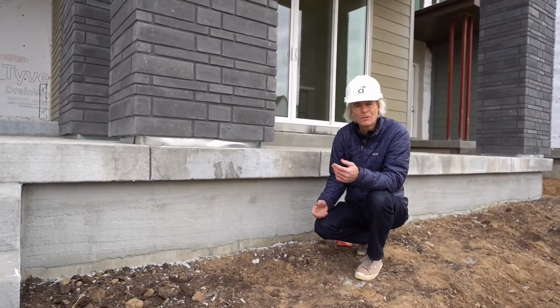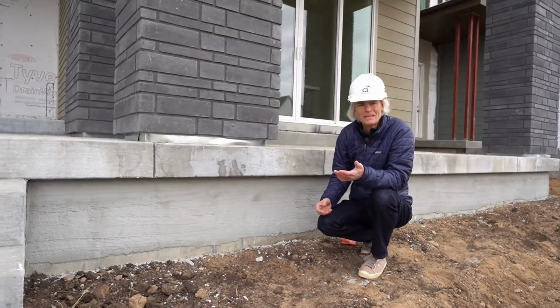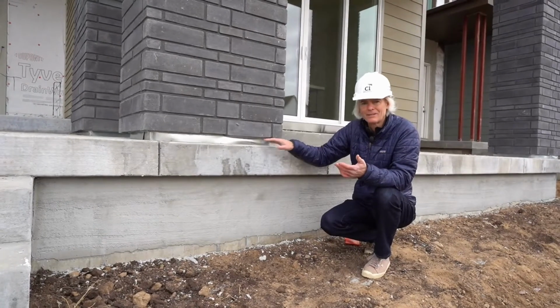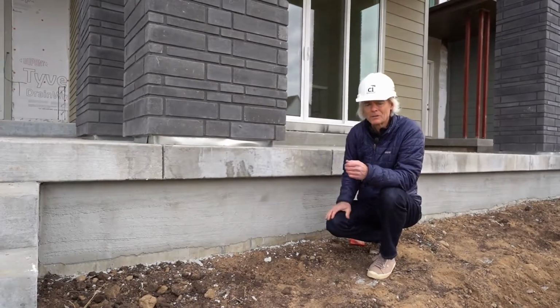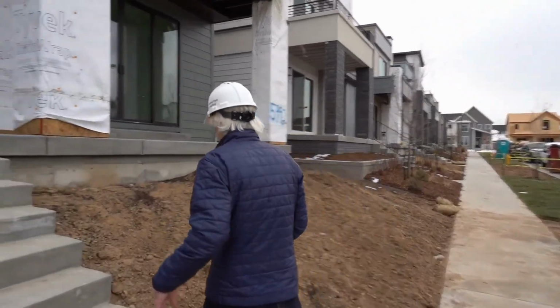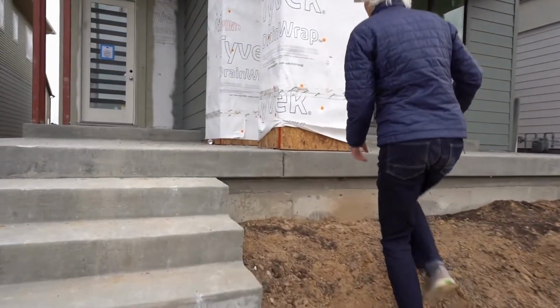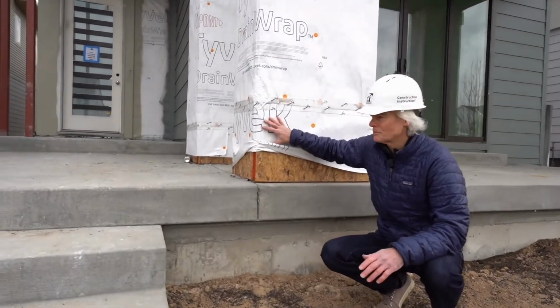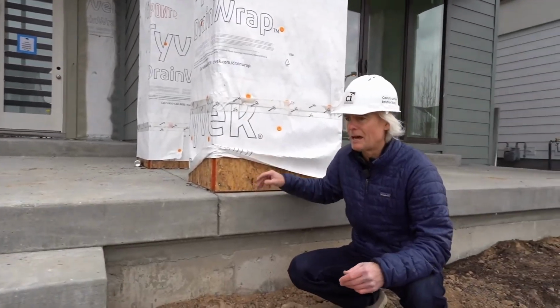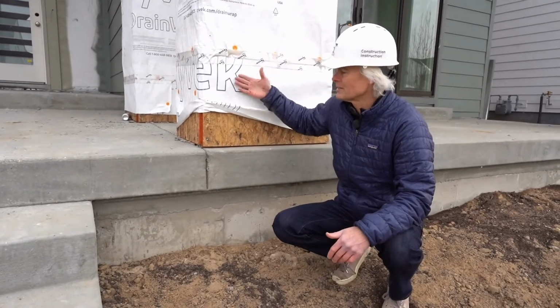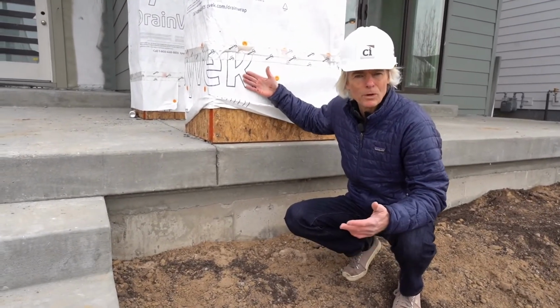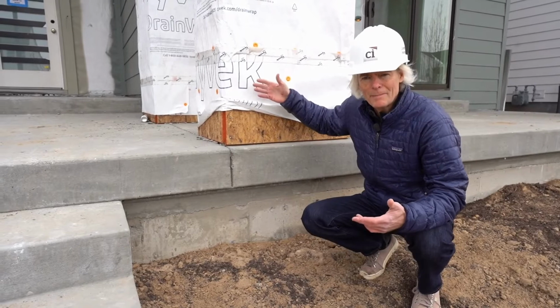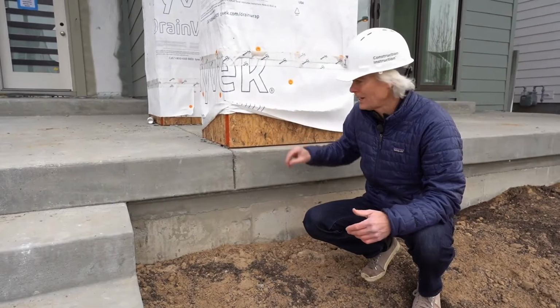But let's just see what the layers look like beneath this to figure out how they're effectively dealing with water on this particular critical application. So here we've got this thin brick prep, and you can see at least they're using a draining weather resistive barrier. That's a really good first step. Next layer you'll see is that the grade D paper will go over the top of this, expanded metal lath, scratch coat, and then application of thin brick.